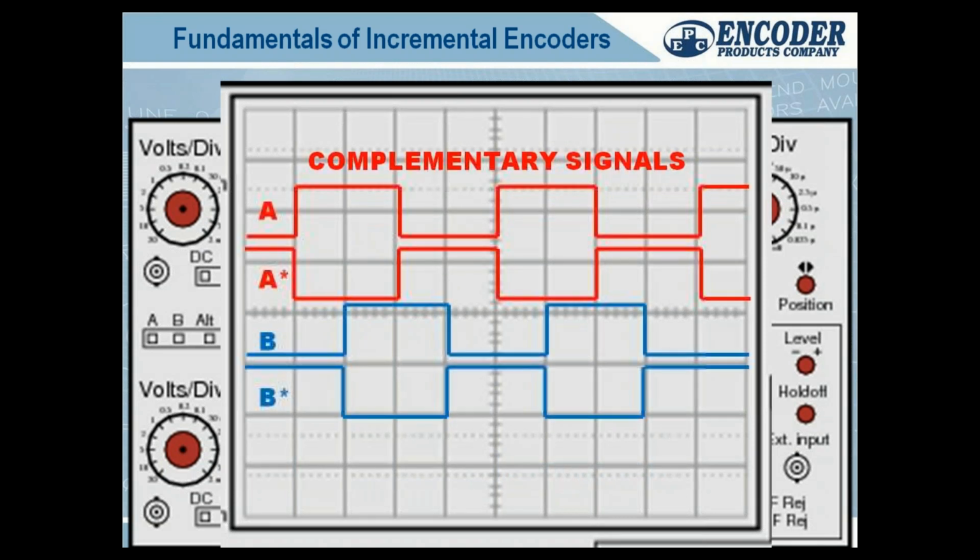So Jared, go ahead. We have a couple questions here. How many RPMs can an encoder handle? In theory, I guess infinite. The limits to RPMs are 2: the max bearing speed, but not all encoders have bearings. Some encoders, which we're going to get to in the next section, are modular. You install the disk and the read head separately so that you don't have the limitations of bearings. At that point, your limit is just the max frequency of the electronics of the encoder itself.